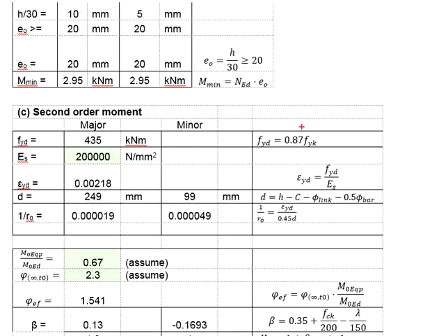Therefore, fyk given in the question is 500, multiply 0.87, you get fyd, design yield strength of 435 Newton per mm square. The modulus of elasticity of the steel is 200 gigapascal. This is given in the Eurocode. Substitute the values into the equation, you get your design yield strain equals to 0.00218. Next, you need the d.